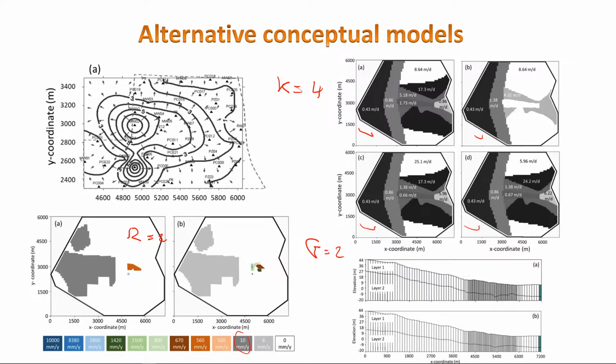What do you do with them? Which is the true model? Well, the true model, let the data speak. Set up 16 groundwater flow models, calibrate these 16 models, which means try your best to make the model match what you are observing in the field. The models that can better represent what we are observing in the field, these are the good models to keep. Some models will not be able to represent what we are observing in the field. This means that this is a bad proposition, a bad idea, and we just eliminate it.